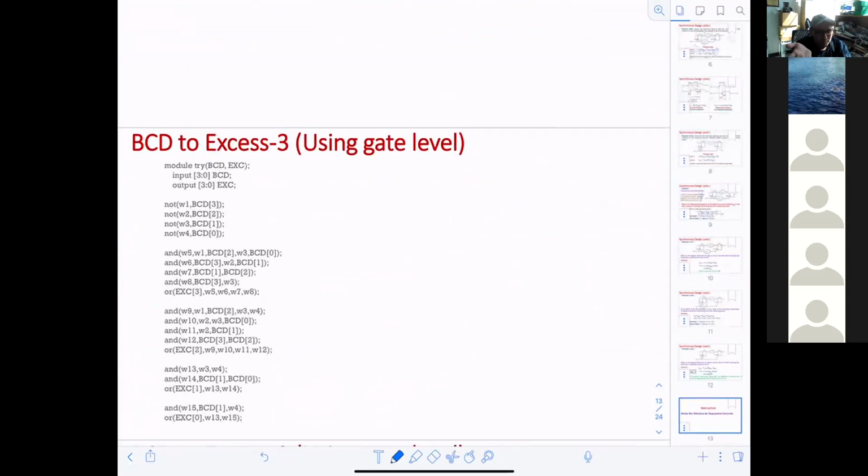So what is the play we play here? Somebody is telling you, can you please build me the gate-level structure of the BCD to excess-3 converter? How many of you are aware of how you can convert from BCD to excess-3? If we know the conversion through gates, off the top of our heads, it's basically you add 3 to the digit. So, think about logic gates.